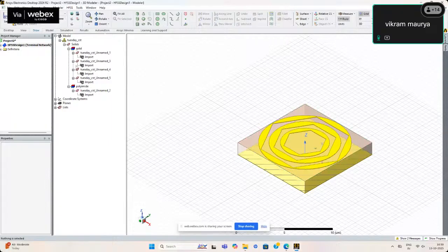And how we can assign this is the, in CST you can apply the boundary condition very easily, because in CST multiple options are there in the boundary conditions, and directly you can tick all these Floquet port or ET0, HT0 and unit cell, open add space or directly open all. You have all these options. You just have to select those options and you can create your boundary conditions accordingly. But in HFSS, you have to make a boundary condition here. You have to make a boundary here.